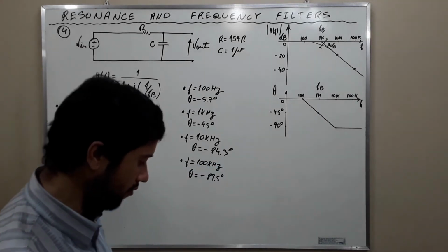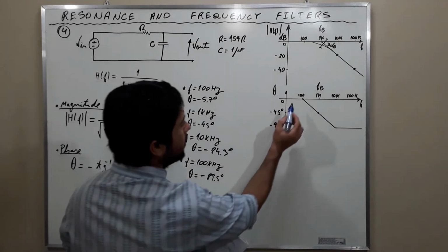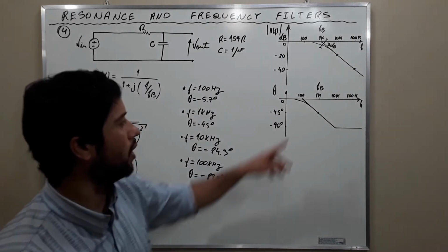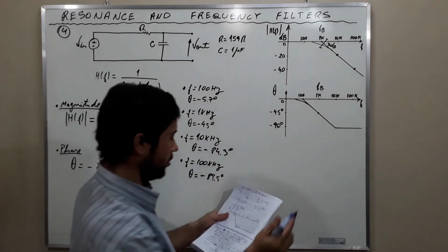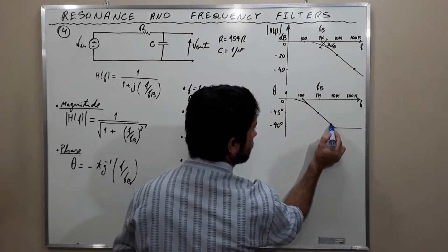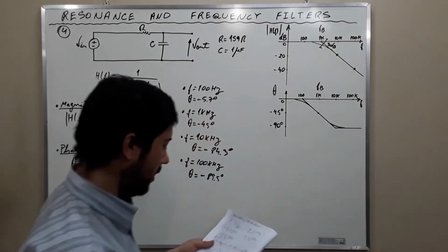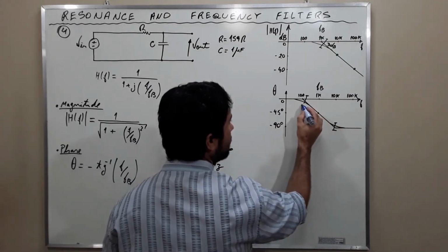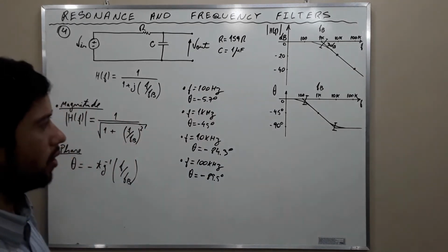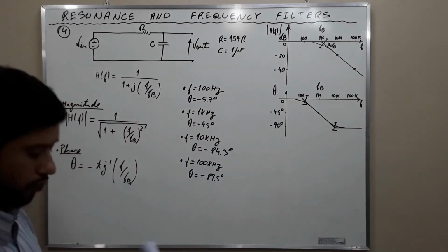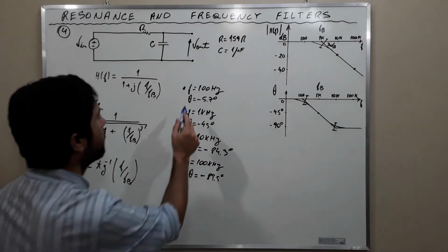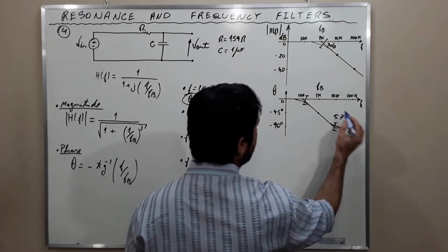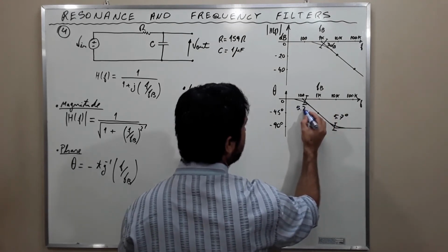to the actual curve. Okay? Here, there is going to be a bending here. Okay? The curve is going to bend here and is going to bend here as well. Okay? And the difference here and here from the actual curve to the straight line approximation is this angle here, 5.7 degrees, and here 5.7 degrees.